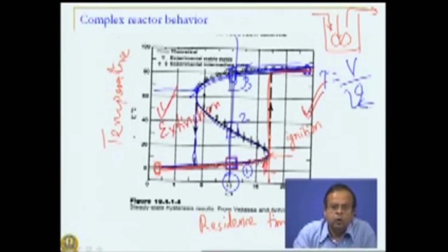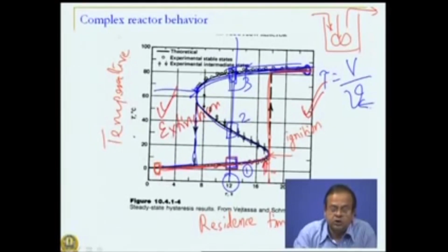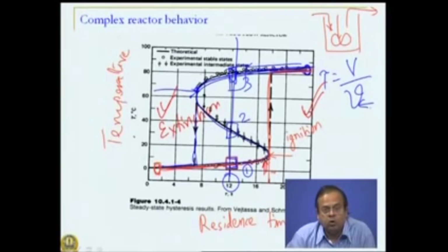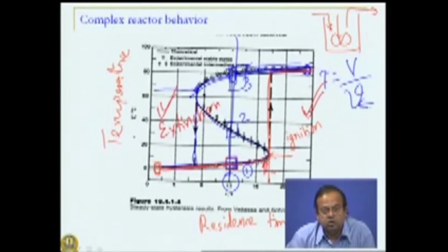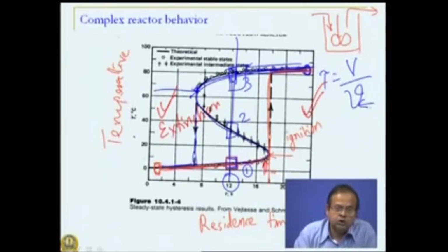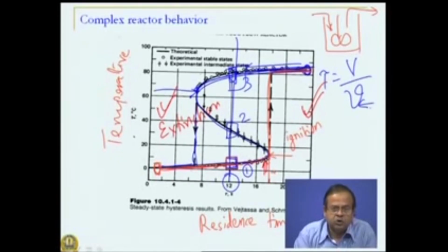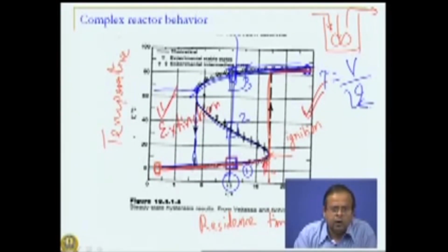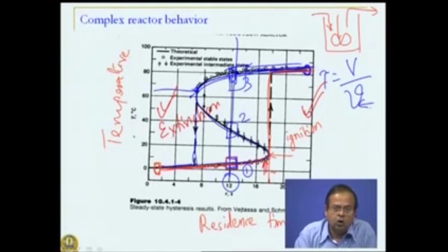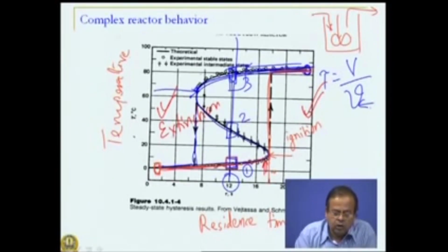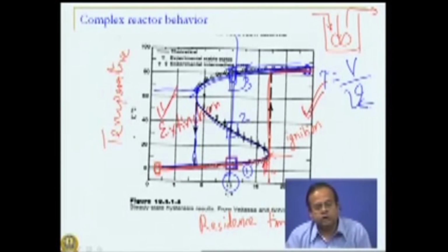Suddenly you would have reaction temperatures becoming very high, a possible cause of an accident. If it is a reverse process, suddenly reaction getting extinguished, not as much a problem, you probably may not have an accident, but still it is a loss, because whatever you wanted to do at high temperature, now suddenly you have low temperatures.